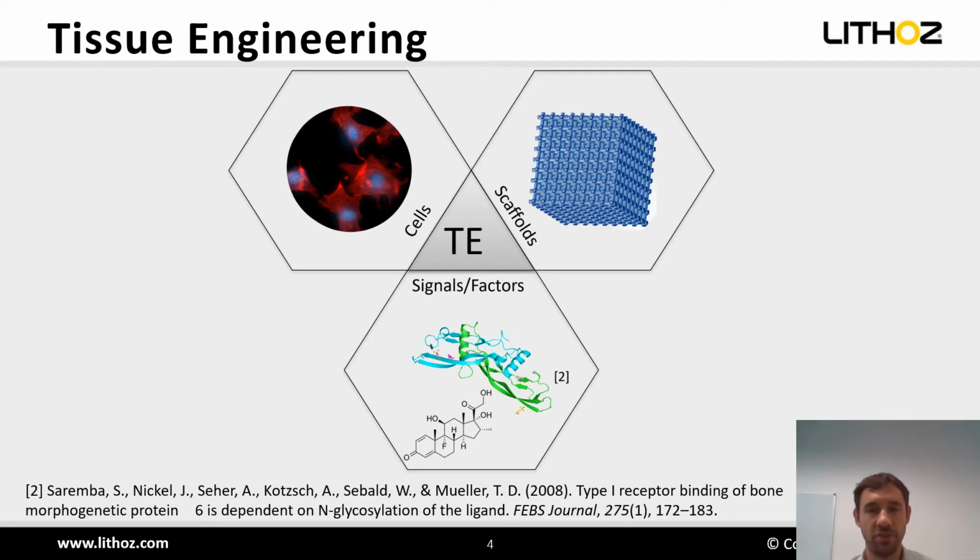So the aim of tissue engineering is to maintain, restore, or even improve different biological tissues. And by using ceramic as a scaffold material, we are obviously targeting here bone replacement materials. And there are certain ceramics, like the tricalcium phosphate ceramic, that is the material of choice here, that have a very similar chemistry to the inorganic content of bone. So if you use that as an implant material, the human body is capable of resorbing that material and remodeling it into native bone tissue again. So this is obviously a very interesting candidate for bone replacement material.